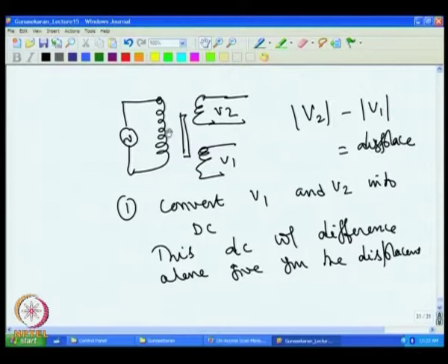So, the resistance of this coil matters a lot, because whatever voltage is applied is partly lost on the resistance of this wire. The LVDT has a resistance in the primary as well as inductance, and only the inductive part is transferred to the secondaries. The resistance is not transferred, it is a loss.